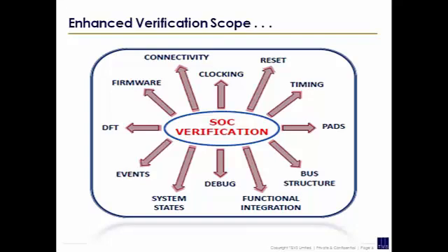So every time the designer feels like, oh, I want to add something more, the verification engineer has to realize that he has 4 new tasks to do. So that's how the complexity of verification is also increasing here. Apart from the traditional connectivity check which we used to do, now we are doing debug support, we have DFT, we check the pads, we have analog and digital mixed parts and how we handle that, and we also take care of system states.